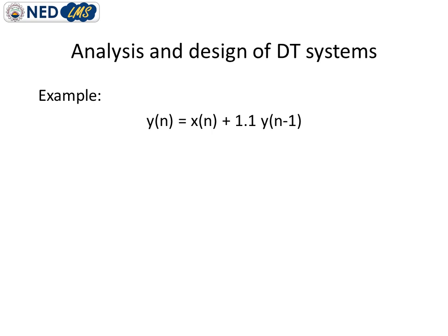So in infinite impulse response systems or IIR filters, we can have infinite impulse response plus diverging or converging response, and another classification is that the response can be single-sided or double-sided depending upon the nature of the system, which you will see when you replace the positive sign with the negative sign.